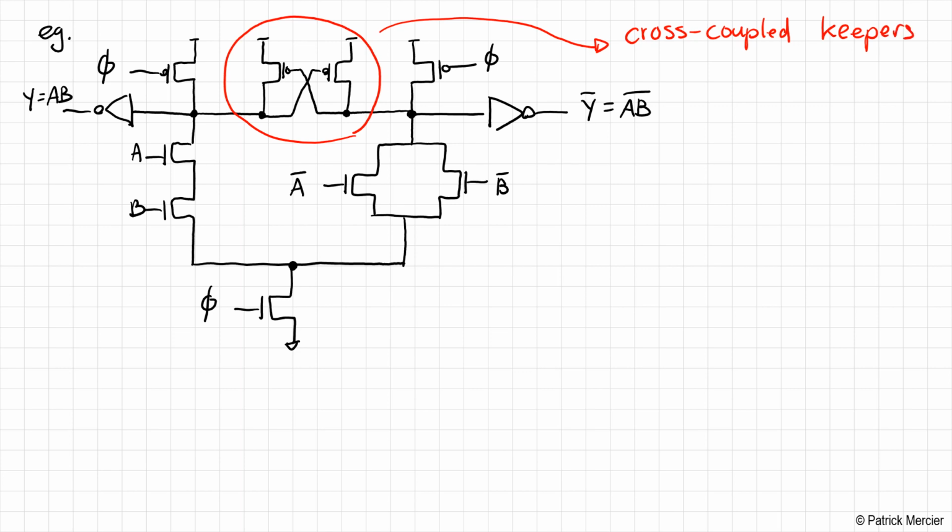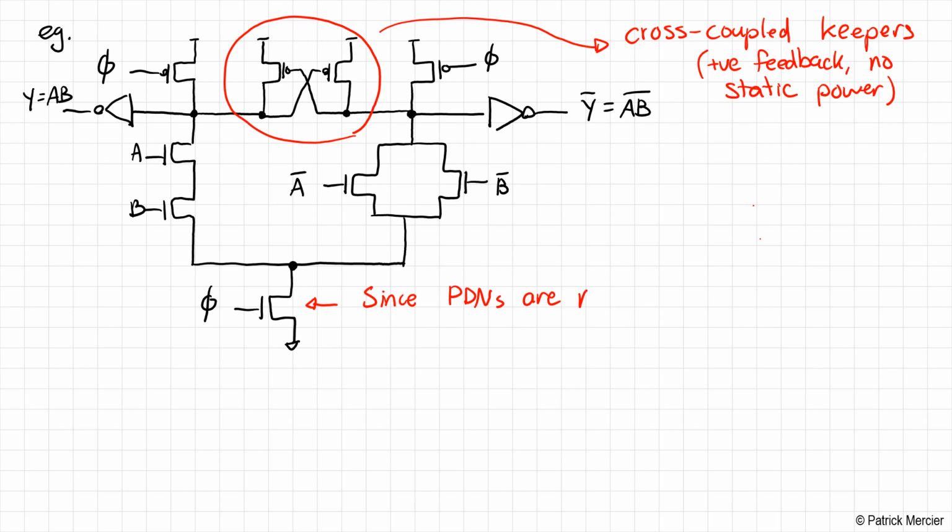Again, it looks similar to the Cascade voltage switch logic family that we discussed earlier, but in this case, it's doing this through positive feedback, which was the same case before, but now with no static power consumption, because we have the footer switch and the header switches that are acting at the right time. Okay. Now, you might have thought that we needed 2 NMOS footer devices for each branch, but it turns out we don't, since the pull-down networks are mutually exclusive.